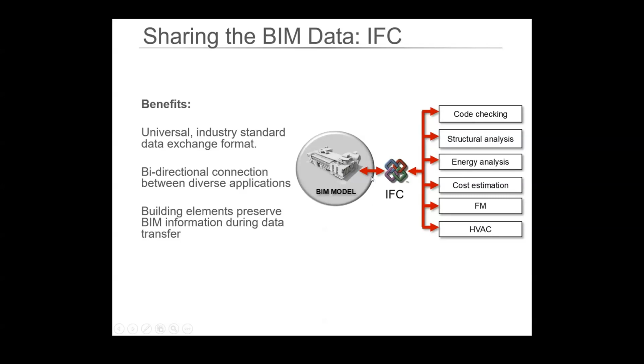So we take this out of our BIM model, and we turn it into an IFC, and then it can be used for all sorts of things. Like code checking, structural analysis, energy analysis, cost estimation, facilities management, HVAC design. So it's not just a pretty picture or something to look good on paper. It's actually being used for a lot more information, a lot more as a tool for the building design process.